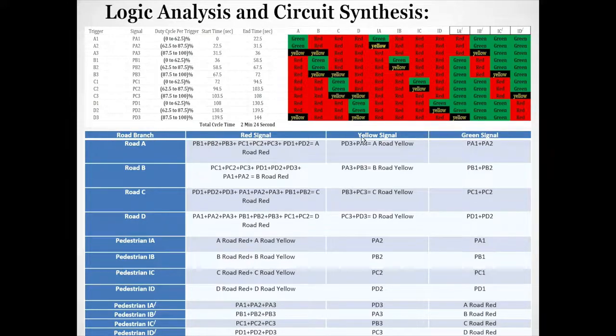When road A has the green signal, pedestrian path IA is free, and before road A turns yellow, the pedestrian path IA is signaled by yellow for the safety of the pedestrians. The rest of the sets of the signal are red for this path. Conversely, when road A is free for the cars, path IA prime is strictly off for the pedestrians and the signal is red. And when road A outgoing is off, path IA prime is free for the pedestrians. This is all about road A.